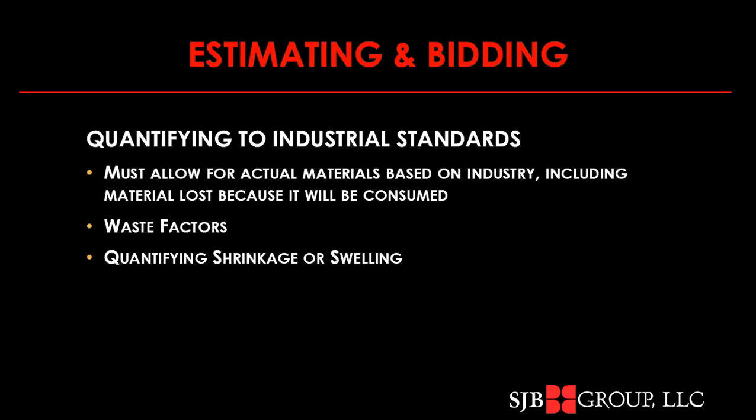You need to consider waste factors. Let's say we're going to have a two-part epoxy, and you mix up the two components. You only have so long to use that epoxy. Well, if you only needed half the gallon, you're going to end up having to waste the other half. So you need to put those waste factors in your estimate.